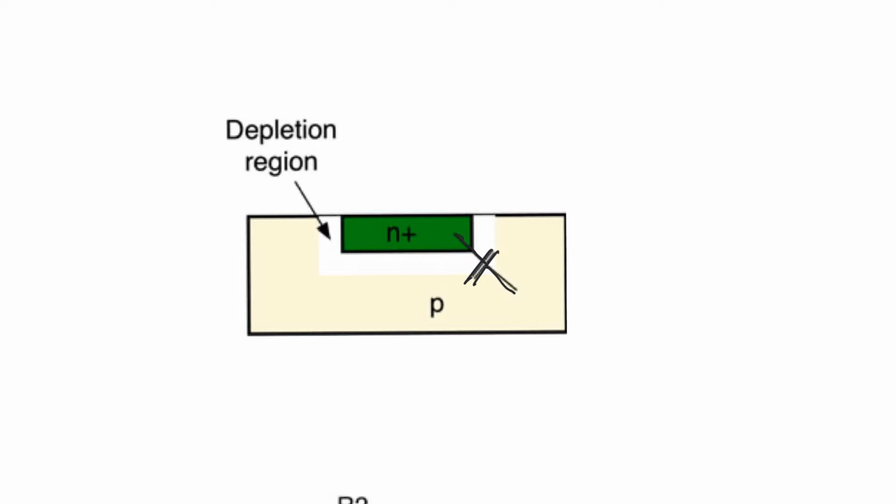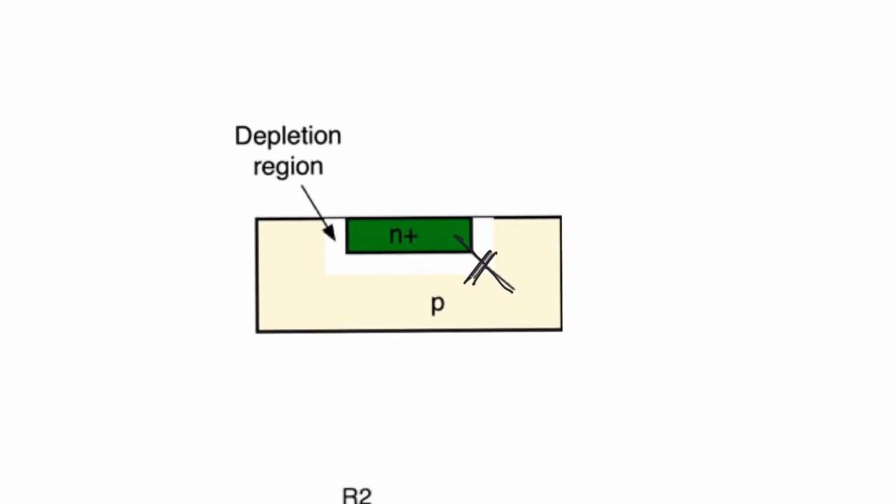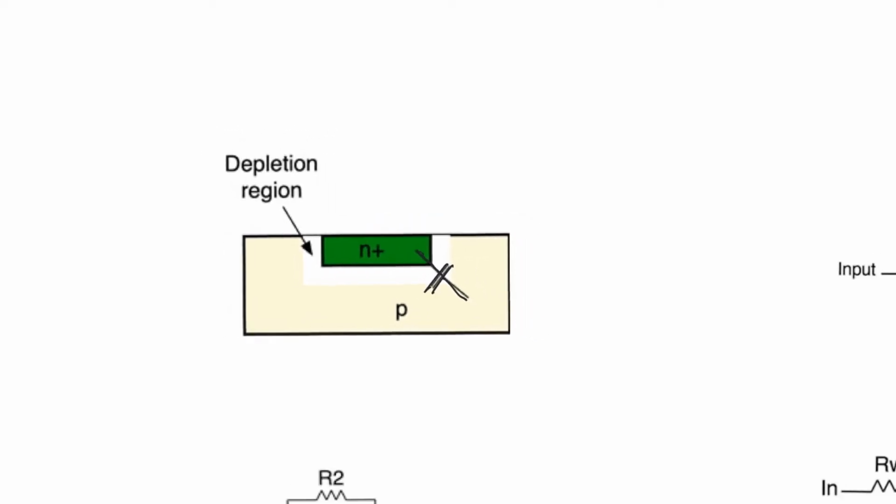Of course, depletion capacitances are nonlinear and therefore we have to use average values. But depletion capacitance also increases with the area of the wire. So we still have to contend with the same trade-offs that we see with wires created at higher layers. Now, resistance also affects metal layers. It's important to stress this, especially in modern technologies which operate at high frequencies and suffer from the skin effect.